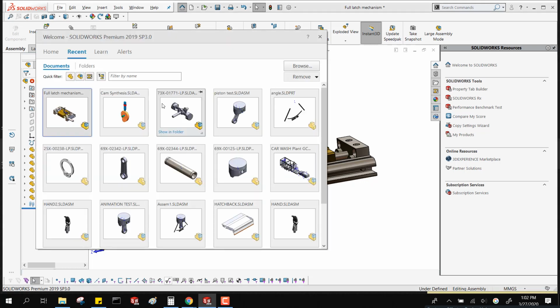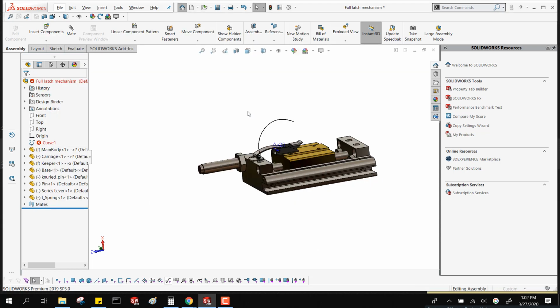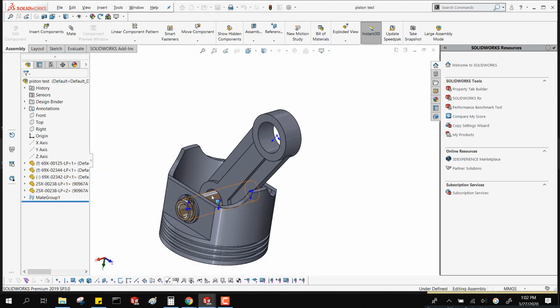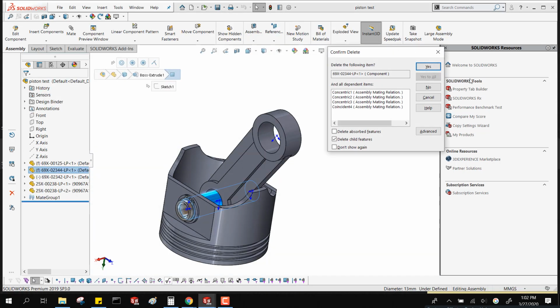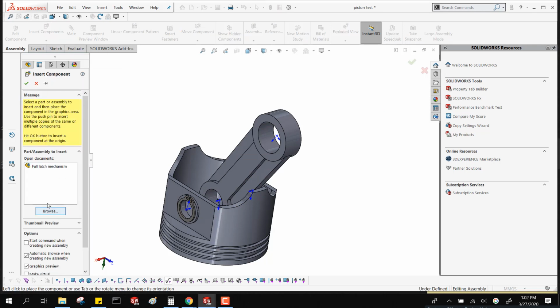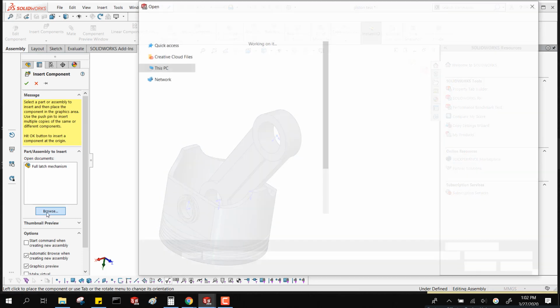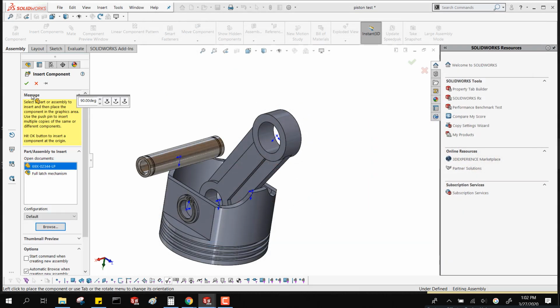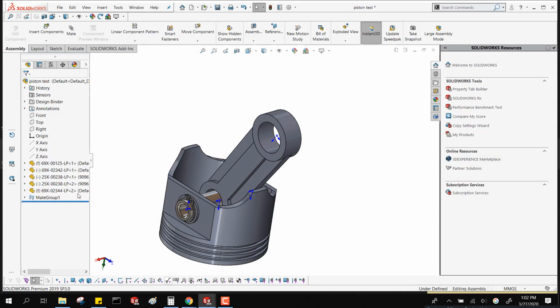Oh, sorry, I missed the first 5 minutes. It's okay. I had the spiel for you, but what I talked about was when I brought this pin in, I can do it again here pretty easily. It comes in just like a master model because I actually modeled the thing in the correct position that it's in the assembly. And that is a great design tool because I know the thing is going to pop in where it's supposed to. And this is the same thing that you get when you do a master model. The thing just appears in the space that it's supposed to be and it's fixed in space.